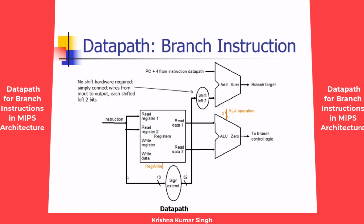The target address is computed from the 16-bit relative address that is inside the instruction part. This 16-bit value will be extended by the sign extension module. Now we have 32 bits. This 32 bits will be shifted 2 times to the left.